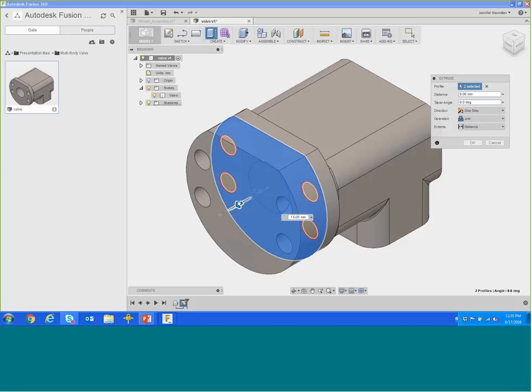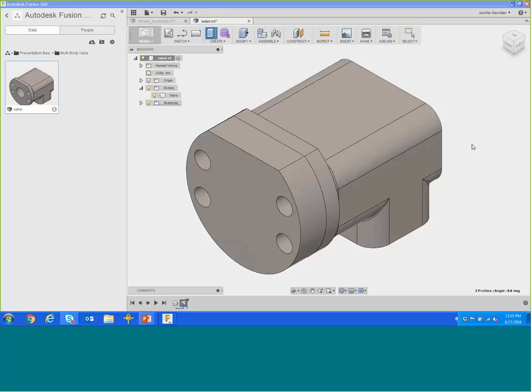And I'm going to drag it out about 20 millimeters, and you can see how it's created that. Now, the extrude panel is over here, and this is what's key with the multi-body design method: by default, the operation right now is set to join. So what that means is it's basically going to join that geometry to the existing body. I don't want that. I actually want to create a brand new body. So I'm going to expand that menu and select New Body, and I can select OK.